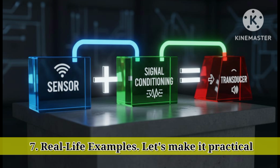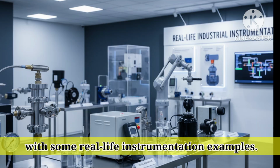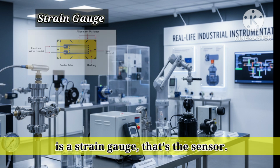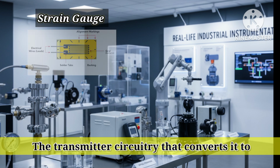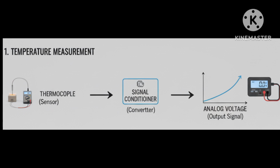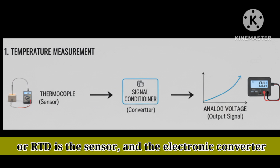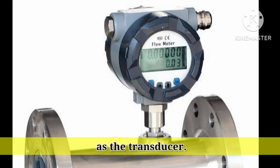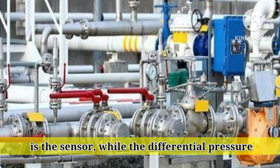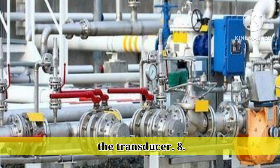7. Real-life examples. Let's make it practical with some real-life instrumentation examples. In a pressure transmitter, the sensing element is a strain gauge, that's the sensor. The transmitter circuitry that converts it to a 4 to 20 mA signal is the transducer. In a temperature transmitter, the thermocouple or RTD is the sensor, and the electronic converter is the transducer. In a flow meter, the orifice plate or turbine blade is the sensor, while the differential pressure cell converting it to an electrical output is the transducer.